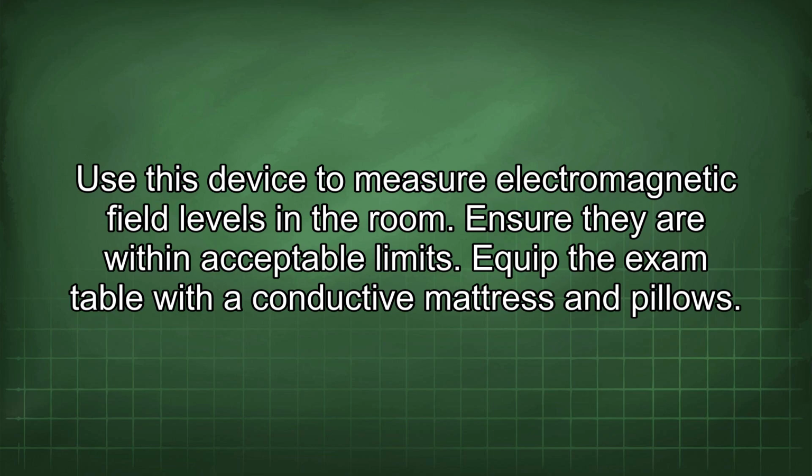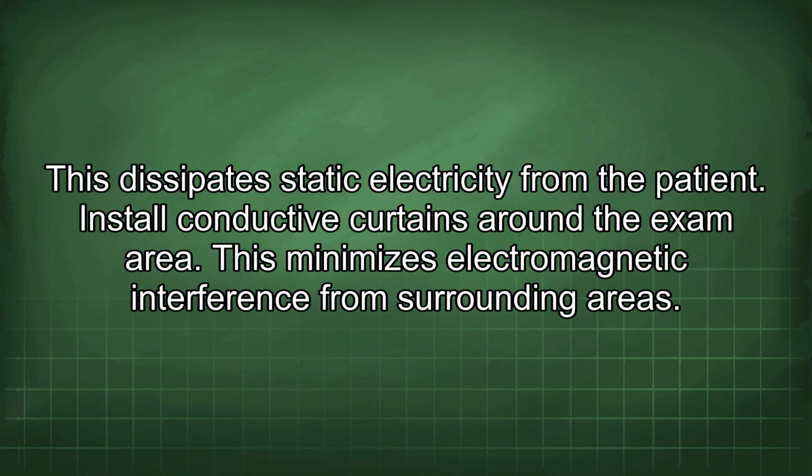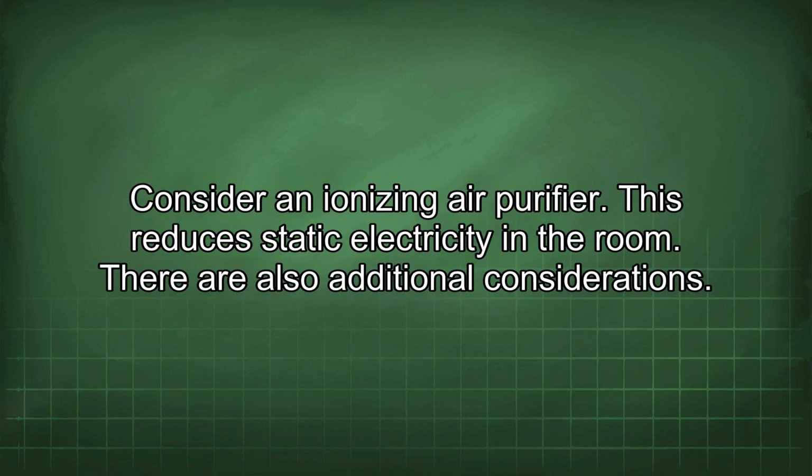Equip the exam table with a conductive mattress and pillows. This dissipates static electricity from the patient. Install conductive curtains around the exam area. This minimizes electromagnetic interference from surrounding areas. Consider an ionizing air purifier. This reduces static electricity in the room.